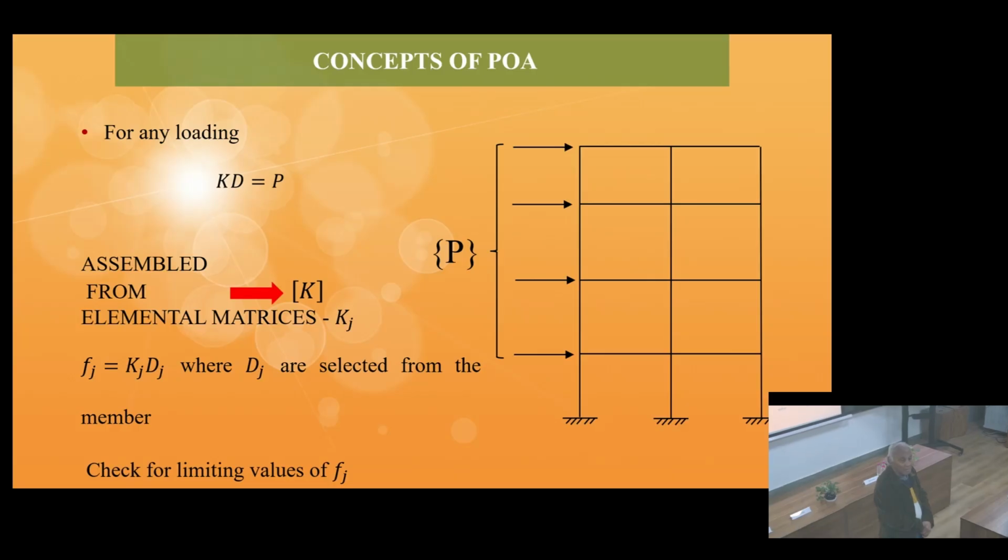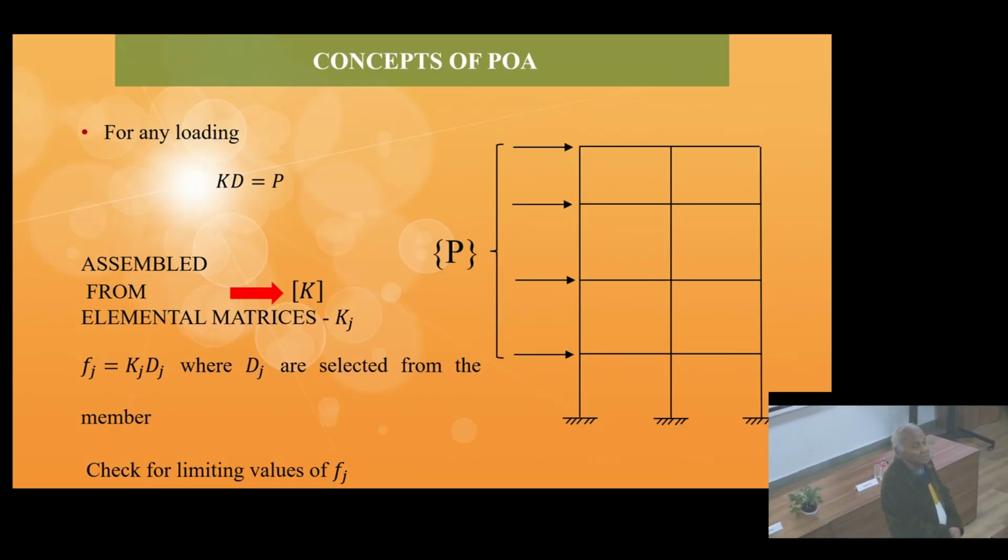This game you have done in your basic algebra. So that is condensation. So in writing down the stiffness matrix, you have the sways, force sways, and rotations. Rotations you condense out, they are the set of variables condensed out, and keep only the 4 displacements. So that's how K becomes 4 by 4.